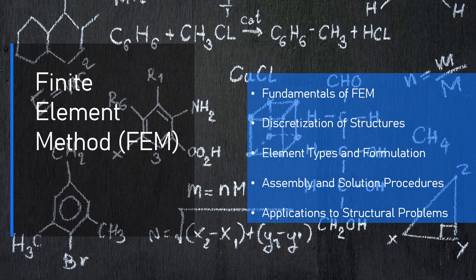Application example: analyzing the buckling behavior of a column under compressive load, or evaluating large deflections in a beam under heavy loading. Benefits: accurate prediction of instabilities such as buckling, snap-through, or post-buckling behavior. Can simulate large deformations without linear assumptions.